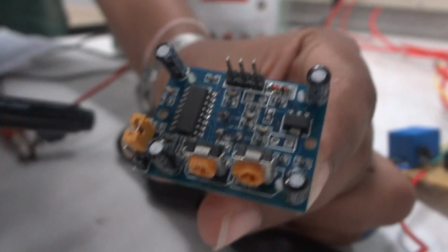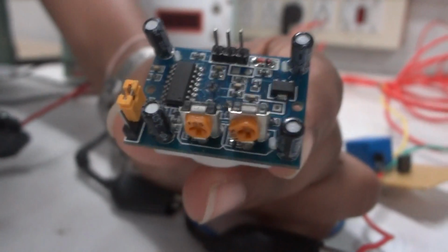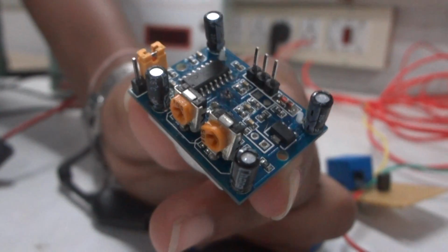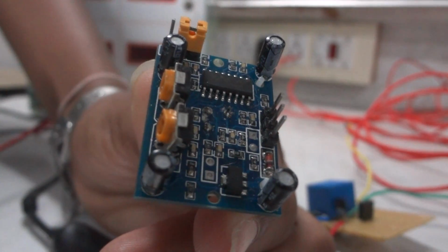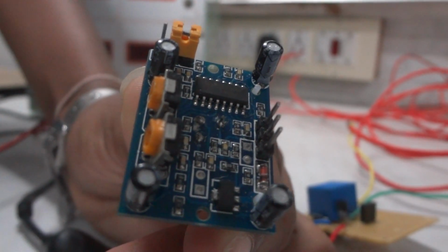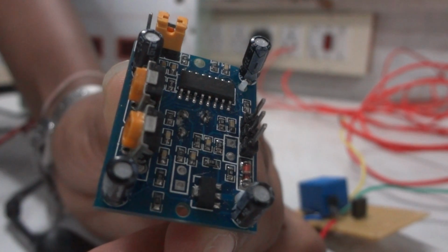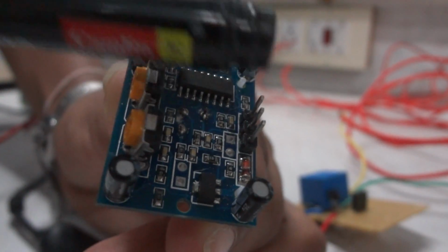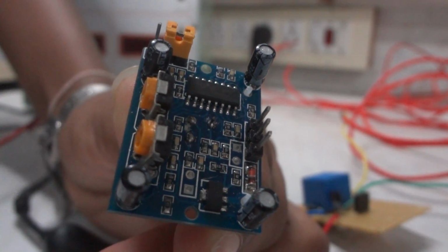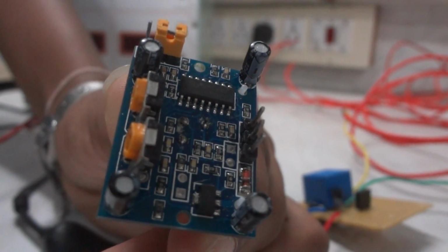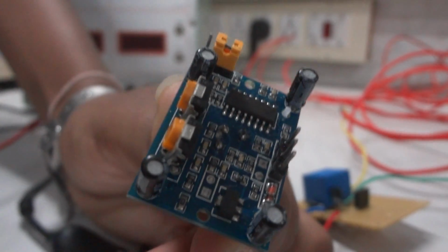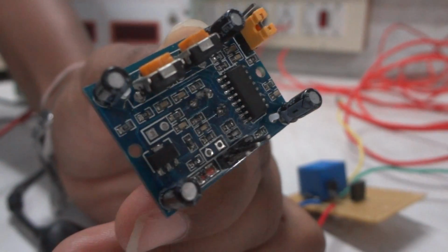So basically the PIR motion sensor is divided into two halves. When there is no motion, both halves remain in the same state, meaning both sense the same level of infrared. As soon as somebody enters the first half, the infrared level of one half becomes high, and thus the output of 5 volt is given to the transistor as soon as the motion is sensed, and this causes the PIR to react and makes the output pin high.